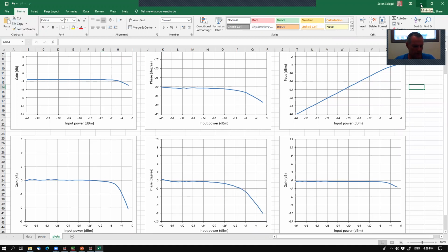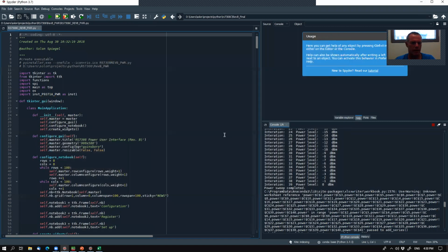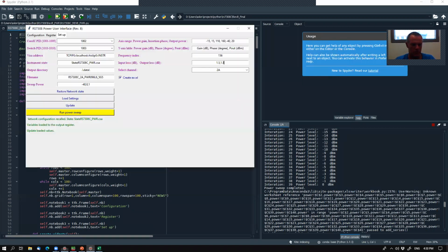So it can have different settings. And this IC, the maximum power, it takes 10 dBm with this particular version, getting a 1 dB compression about 8 dBm at the IC level, at the maximum setting. So we have not displayed it, but the power sweep is also automated. And if you want to do it for many channels, your power sweep has to be automated, the setup as well.